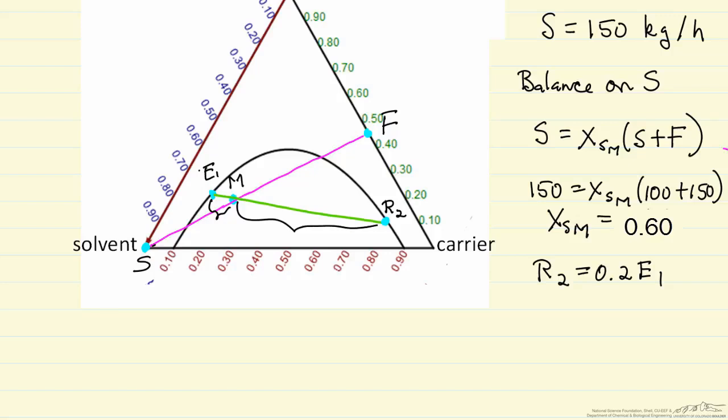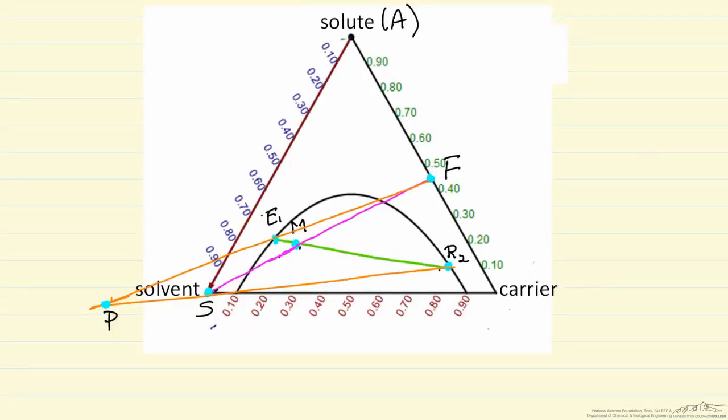What we want to do now is another mass balance to get the operating point. So we found the mixing point, and that then defines, once we have sufficient information, in this case specifying the extract concentration, defines for mass balances the raffinate leaving the entire system. So I have identified this operating point, and this is what I use in determining number of stages.